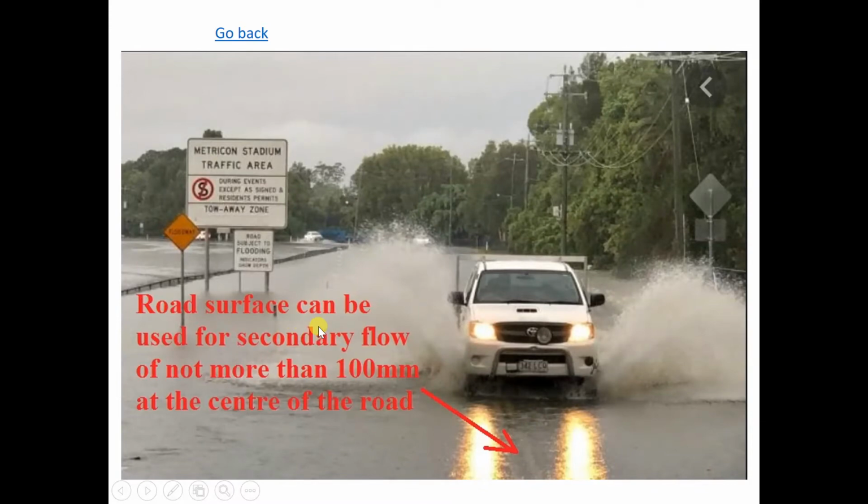So that means for this secondary flow system, we limit it to, let's say, a 1 in 20 years event. The road surface can be used as secondary flow, but we design it so the maximum should be not more than 100 mm, so that it still can be used by the traffic.